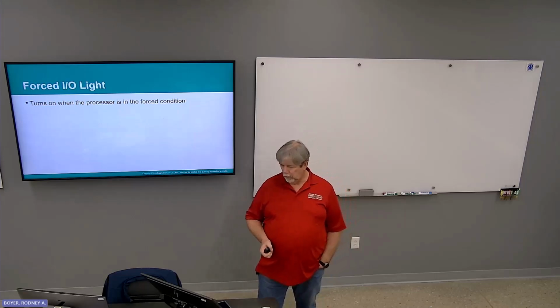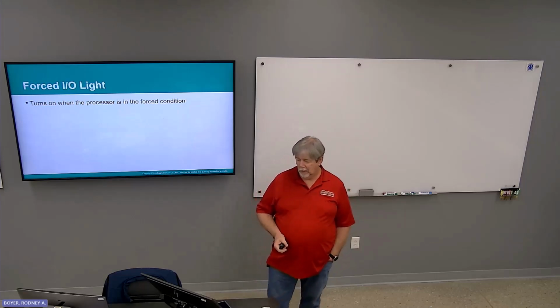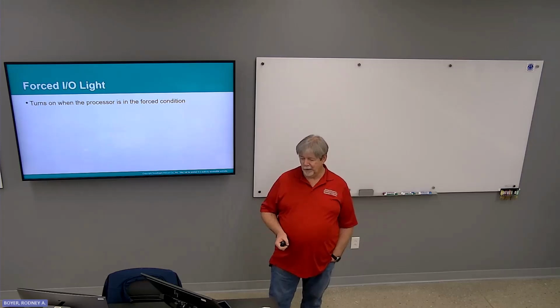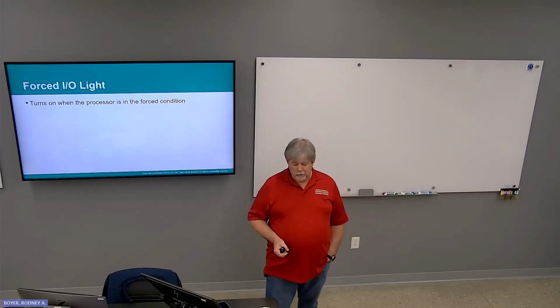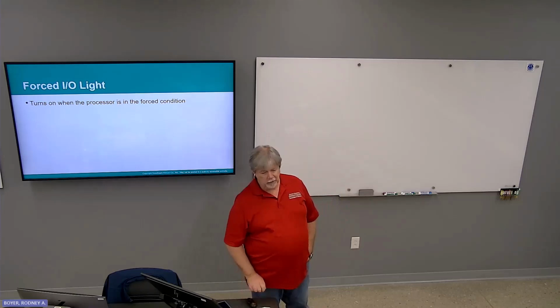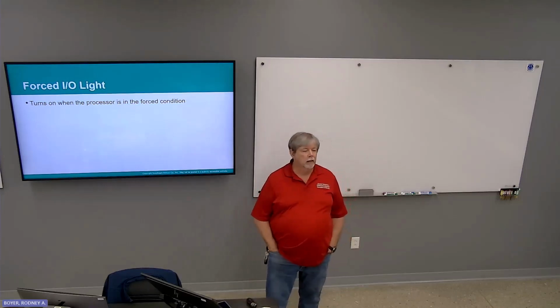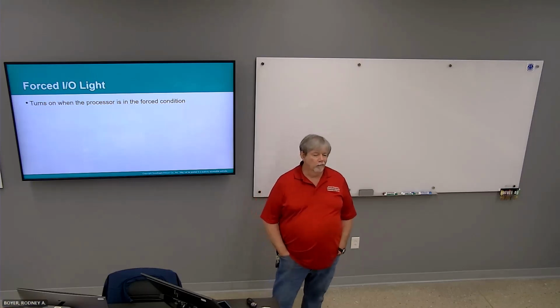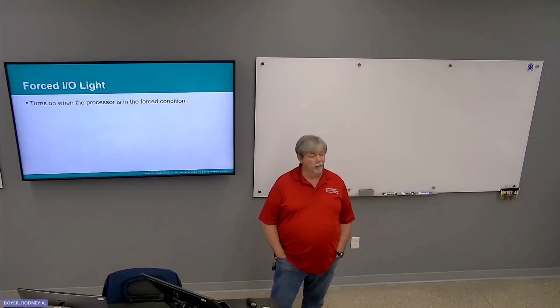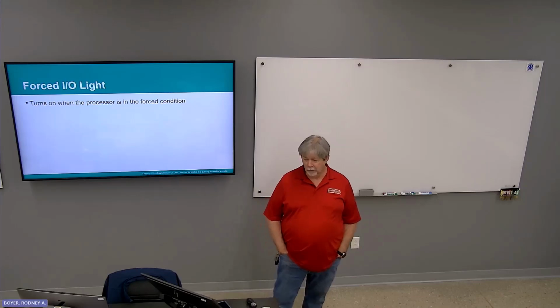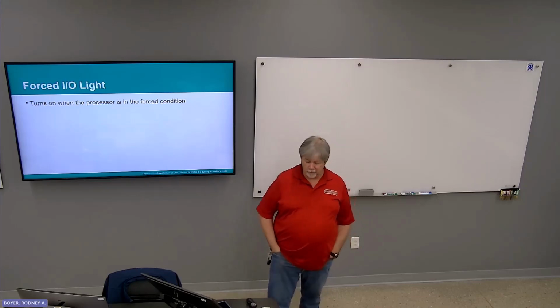Force IO turns on when the processor is in a force condition. Force is to be used very sparingly, very intentionally, and whatever you do, don't leave an input or an output in a forced condition and put the processor back into production, because people tend to get hurt that way.